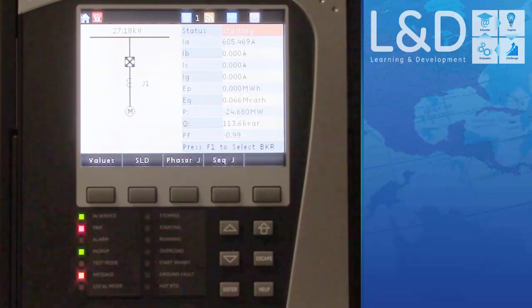And this is the FlexLogic equation we programmed in this drag and drop editor. Compared with the old reverse Polish notation editor, this is a much faster, easier way to program the FlexLogic equation. And that concludes this demonstration of the FlexLogic editor in the 8 Series setup software.